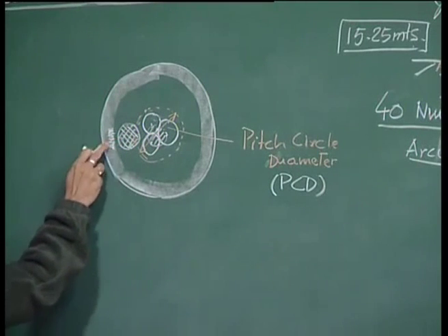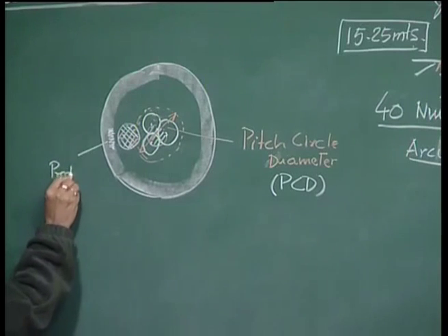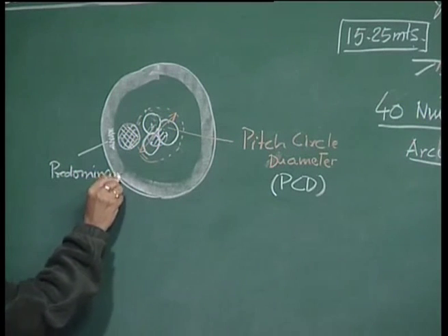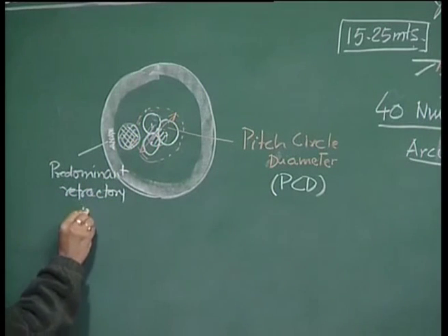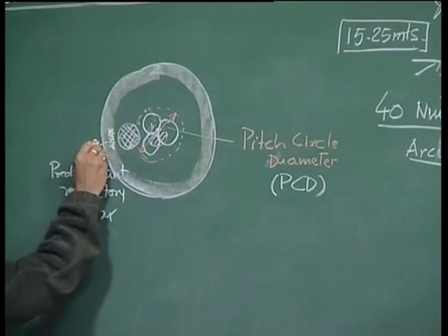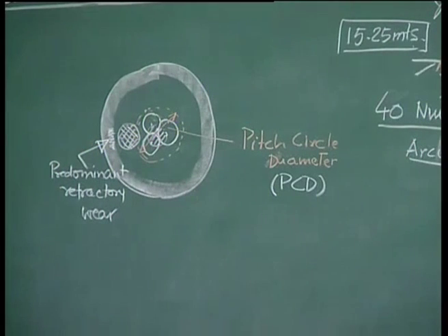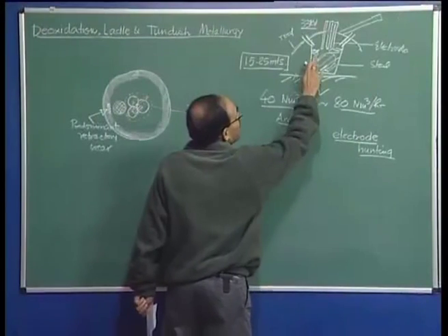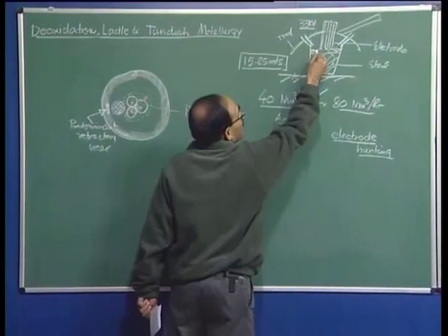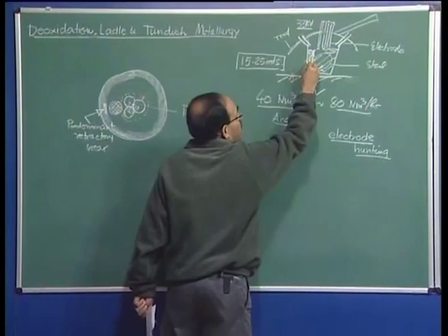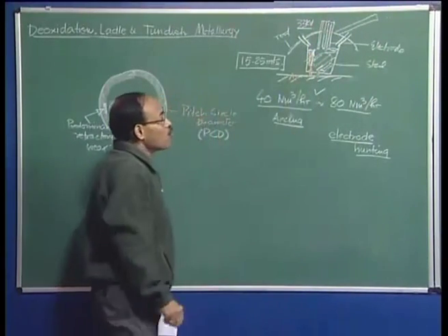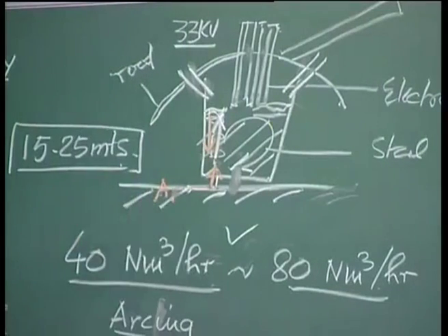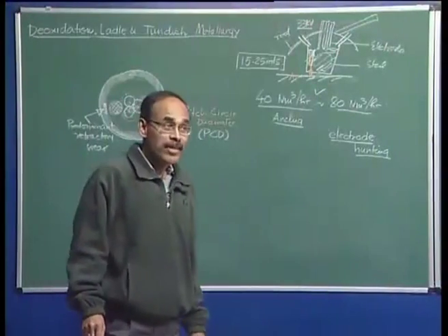So, therefore, you will see predominant refractory wear in the vicinity. So, this is the region where we are going to see a considerable amount of refractory wear. Why is it so? Because the bubbles are rising here, the high velocity regions are located here. So, it is a very high downward velocity which comes close to the wall, okay, and as a result of this high downward velocity, which is shown by a red arrow here, the hydrodynamic erosion of the refractory bricks is very